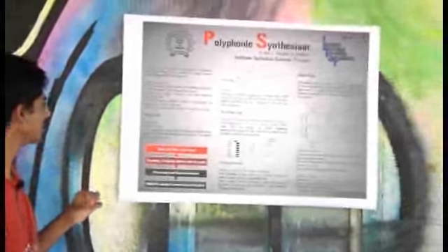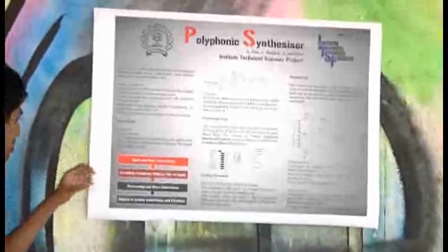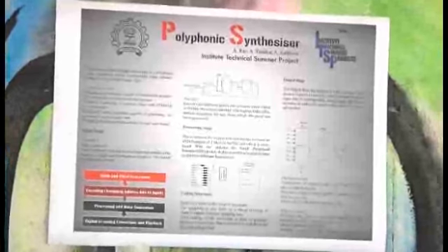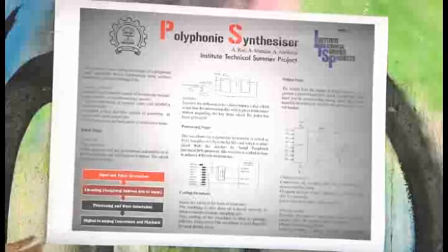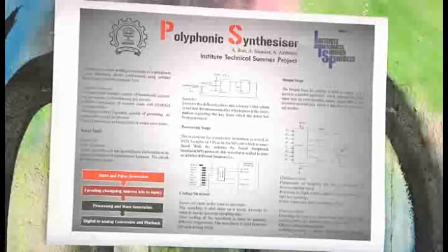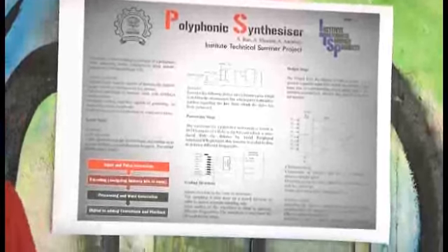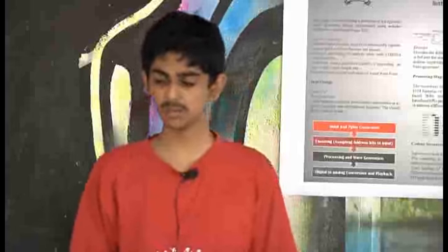The most challenging among these was the input stage, because we needed to design from scratch a system that would enable us to register multiple key presses. A simple way of doing this would be to connect all the keys to the microcontroller, take all their signals, decide which one is on and which one is off, and then play the notes accordingly. But this is not feasible because in an extended setup, considering 12 or 13 or 20